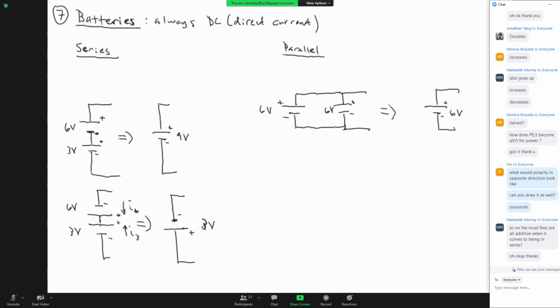Depends. In a series, if you lose one light in your series light for your Christmas lights, the whole chain of lights goes out, right? Because it breaks the circuit. But if you're in parallel, if you lose one light, the chain of the circuit still continues and you can have current still flowing to the rest of your circuit. So in parallel, only the light bulb that's broken goes out, not the whole string of lights. Does that make sense? For difference between parallel and in series?